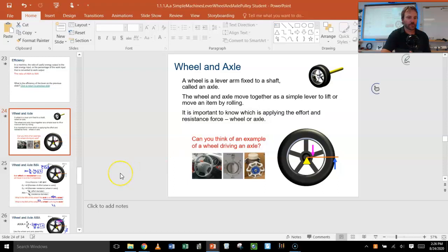That's our tour of wheel and axle and pulleys, and how to find their actual mechanical advantage: AMA, forces. And ideal mechanical advantage, IMA, distances. And with pulleys, you just count the strands. It's pretty straightforward and kind of nice.